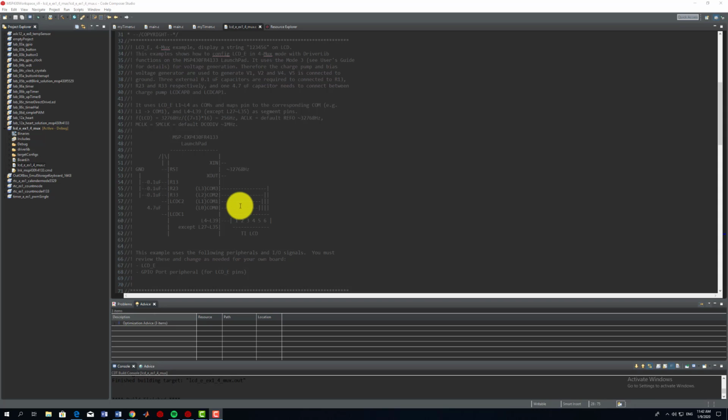For the FR4133, it can use up to 8-mux, meaning the pins we're going to use, the segments and the communications, are muxed together to limit the number of pins. Ideally for MSP430, the very purpose of the muxing is to minimize the use of pins, because the number of pins usually represents the cost. The greater the number of pins, the higher the cost of the LaunchPad.